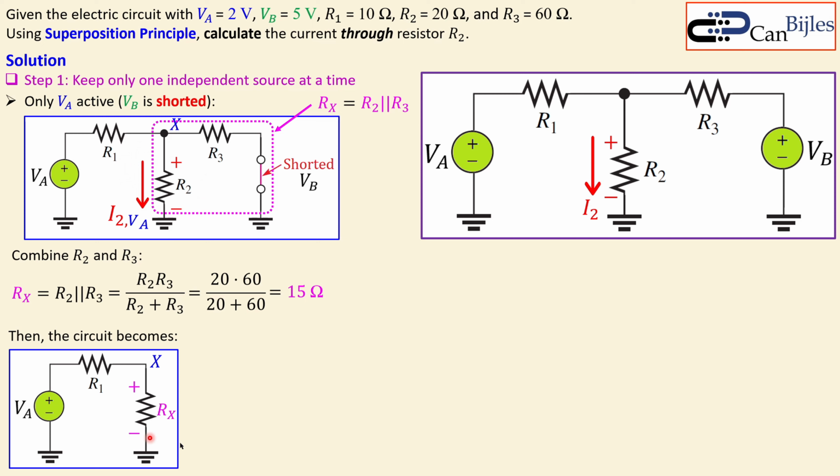So when you do that, you also have your voltage. And if you know your voltage, you can use Ohm's law by dividing that voltage over this R2, and you have your current specifically only for this circuit. So using the voltage divider rule, you will get this expression. That means Rx over the summation of these two resistors times the VA, and it will give you the Vx, which is the voltage across this Rx.